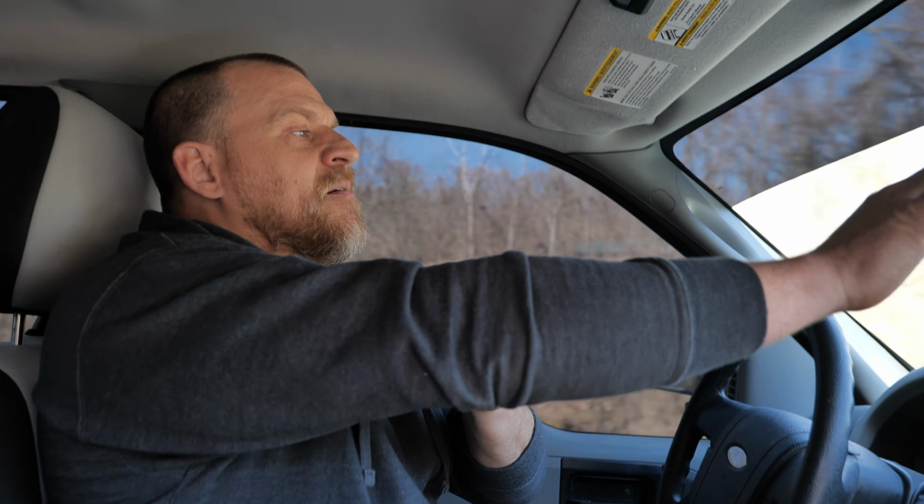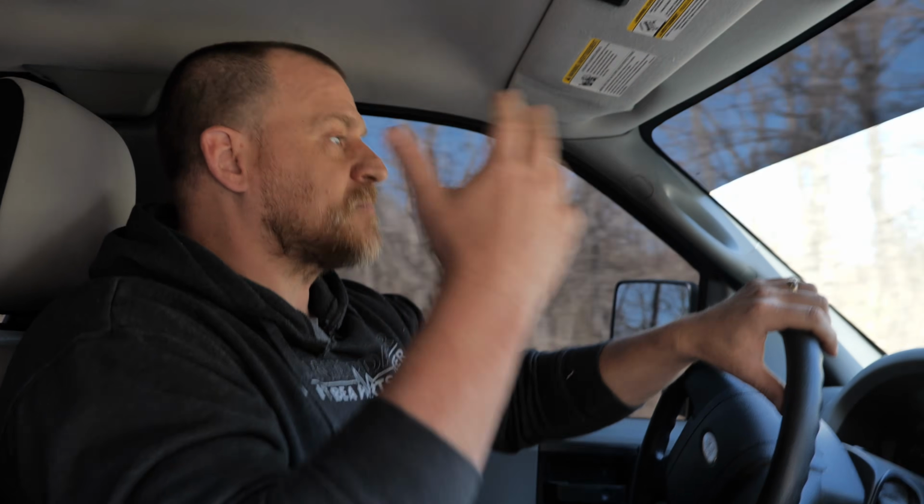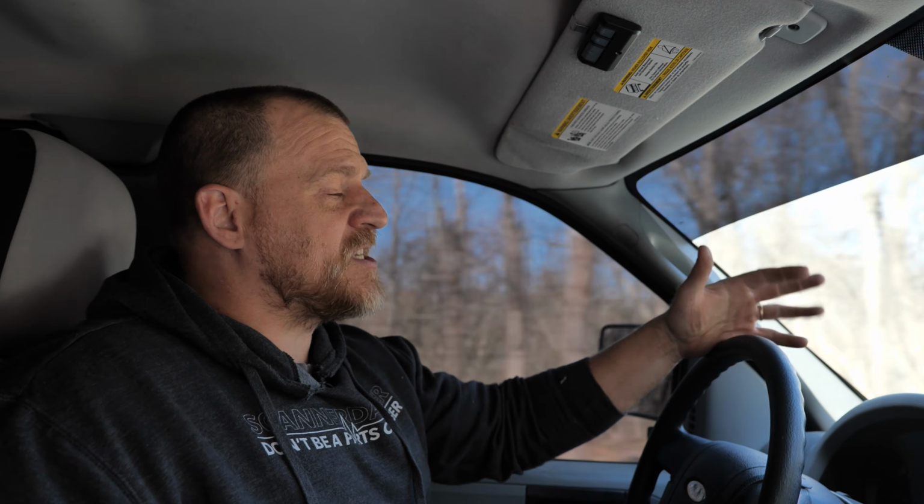This being a mass airflow engine, generally we don't see a MAP sensor causing the same type of drivability problems it would if this was a speed density engine, meaning no mass airflow. But the question is still valid: when you see a MAP code, is the engine running poorly, causing that MAP code, or do you have a MAP sensor problem that's making the engine run poorly?